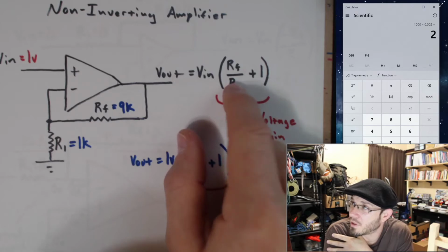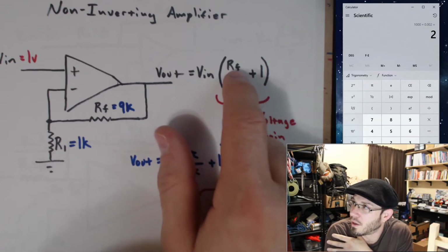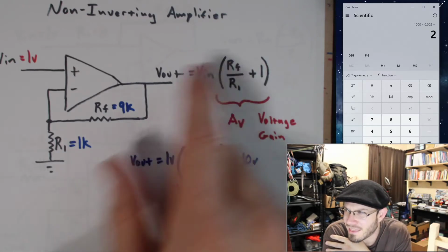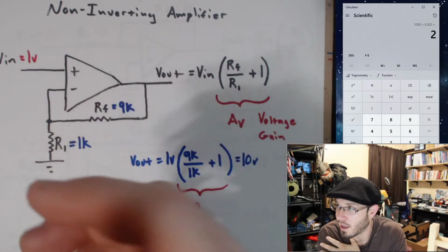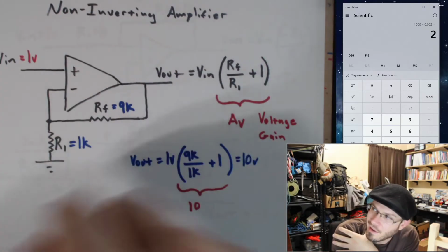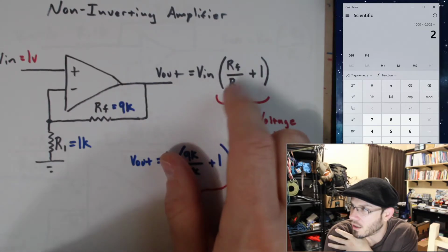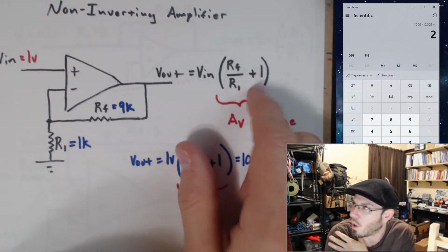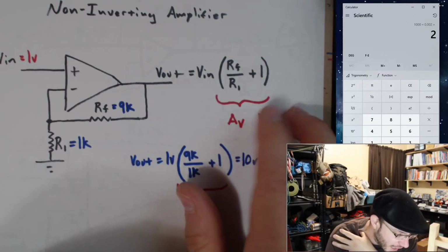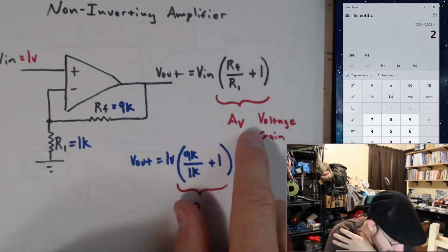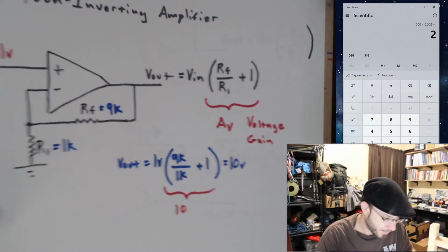Put a big resistor on R1, put a very small resistor on RF, and this circuit's not going to work due to some practical limitations of dealing with real op amps. Even though in our ideal sense on a board it might work out to get something very small here, like a gain close to 0, and then 0 plus 1, and you're like, hey, I have unity gain, and it's non-inverting. It doesn't work that way. So you're really limited to gains above 1.